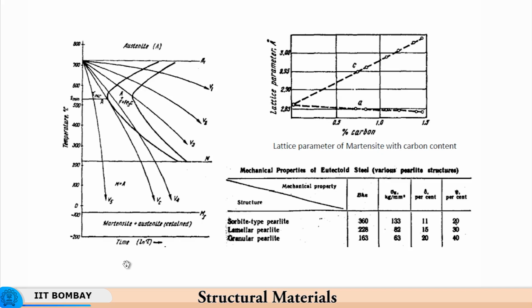So, mechanical working in a way shifts the martensite start above the room temperature. Again, the chemical composition also matters. It is not that any step to adjust martensite start and finish can be done in isolation. You need the right kind of chemical composition also to adjust these martensite start and finish temperatures.